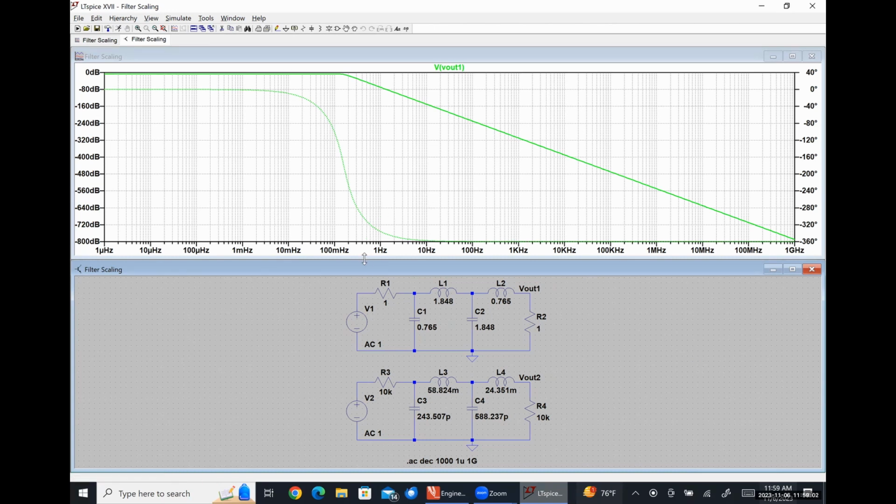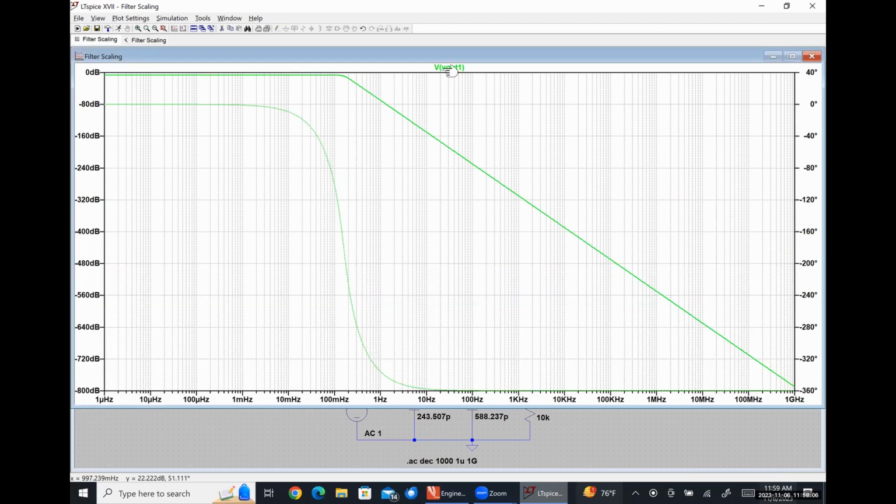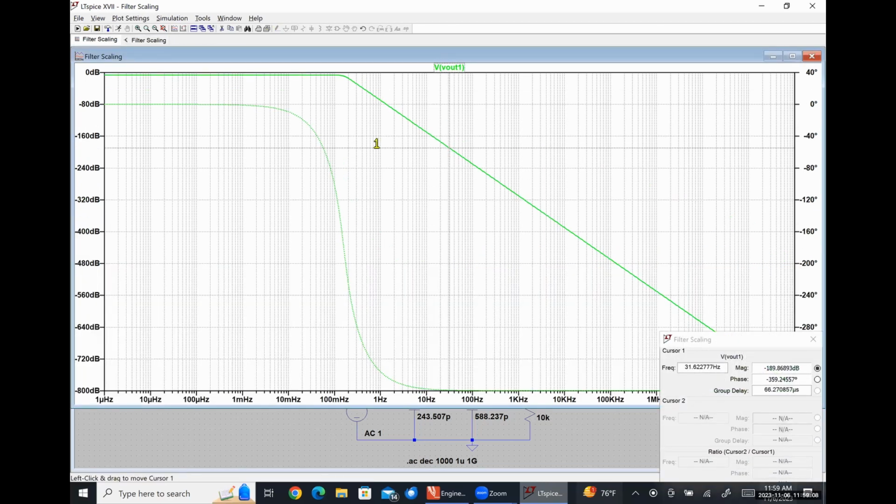Let me move this down here really quickly. So we can see that at very low frequencies, we're at a magnitude of -6 dB, which means our output voltage is roughly 1/2 of our input voltage, which makes sense because at very low frequencies we have a simple voltage divider circuit where we're looking at the voltage drop over one of those 1 ohm resistors.